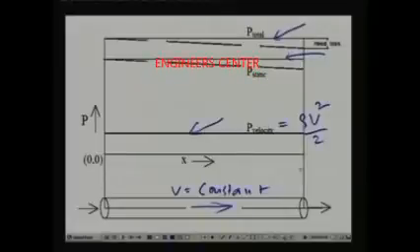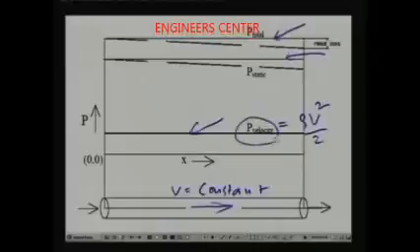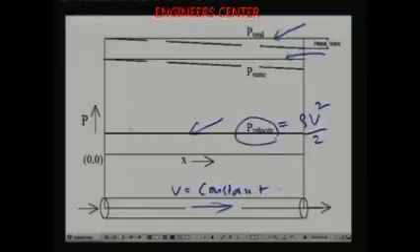So this is the application of Bernoulli's law to an ideal fluid. Now what is the effect if viscosity is non-zero? That means if the fluid is viscid, or it has finite viscosity. For viscous flow, the velocity pressure still remains the same, because from the continuity equation velocity at any point should remain the same. Okay, so this horizontal line applies to both inviscid as well as viscous flows. So velocity pressure remains horizontal only.